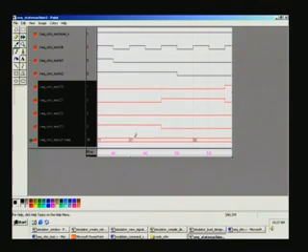So, naturally that state's output must get reflected only at the positive edge of the clock. Any sequential machine will have this always delayed by a clock, and that is not a handicap, because we always have a very high clock frequency, and no user can notice the difference, and no erroneous operation can take place, because the whole thing is synchronous.